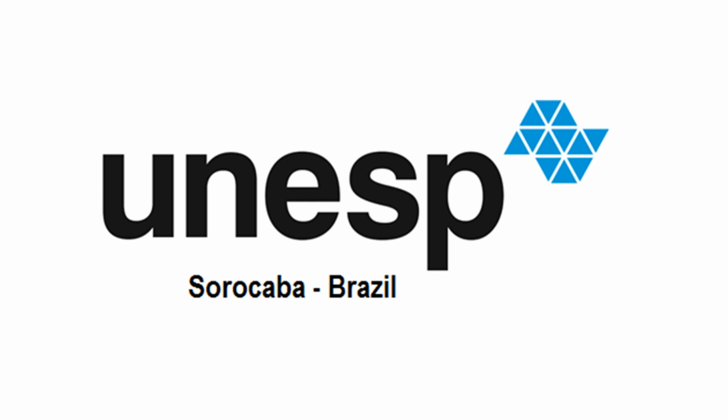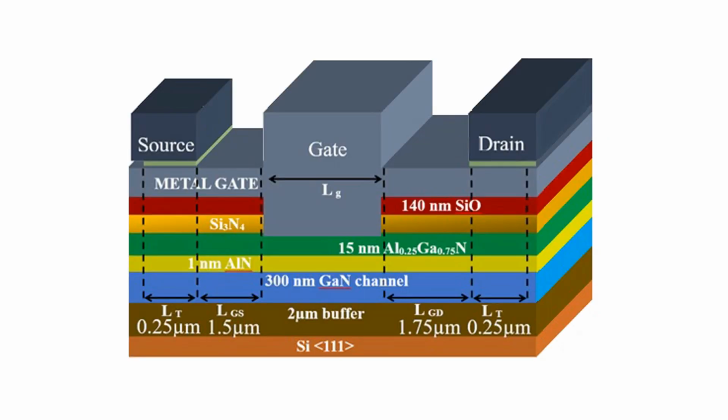High-mobility electron field effect transistors were previously developed for high-speed applications, and due to their low noise performance, are currently widely used in small signal amplifiers, power amplifiers, oscillators, and mixers operating at frequencies up to 60 GHz. High-mobility electron field effect transistors are of great interest when applied in radio frequency circuits and analog circuits due to their properties such as high frequency, high electric breakdown field, and high saturation speed.